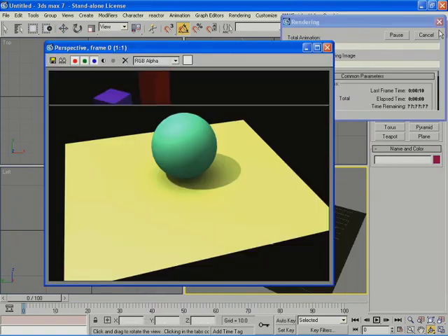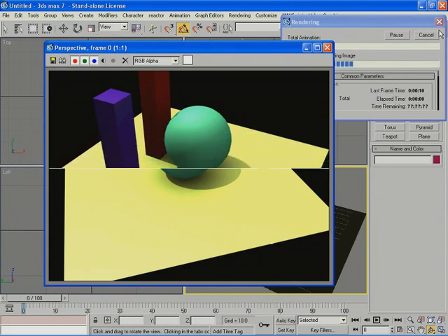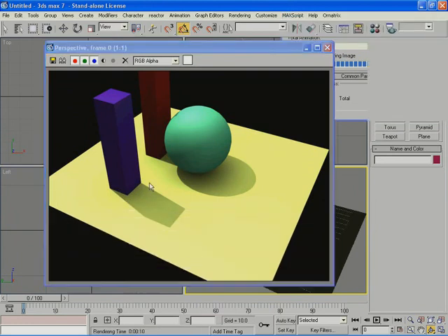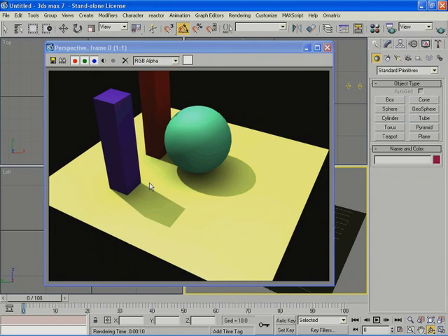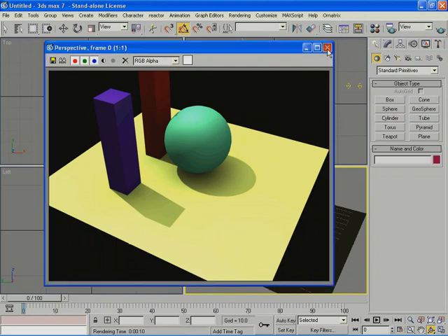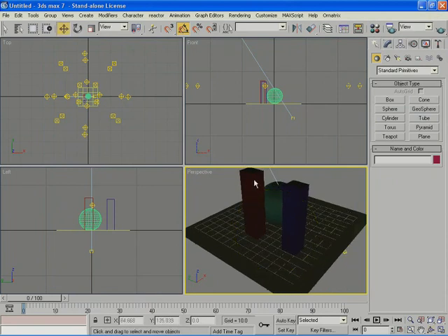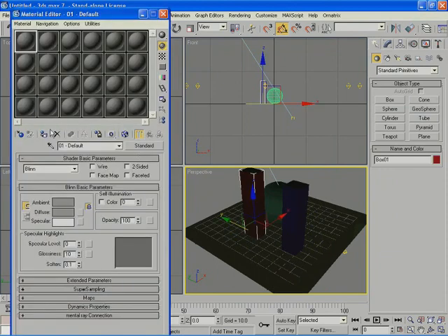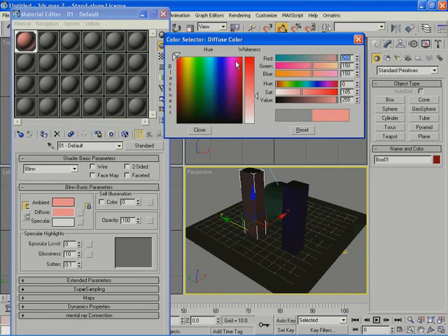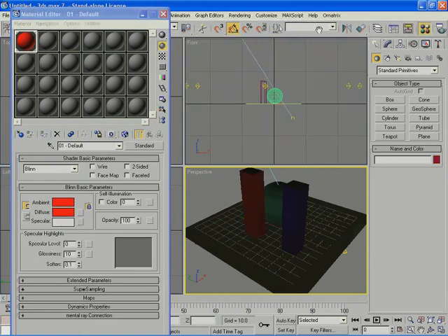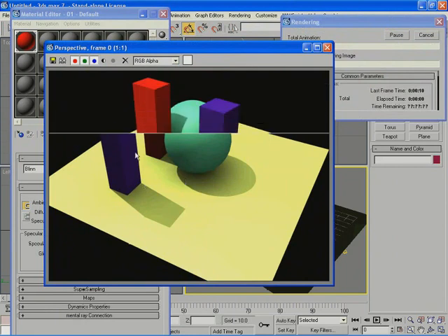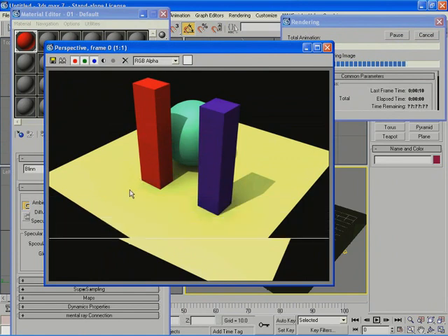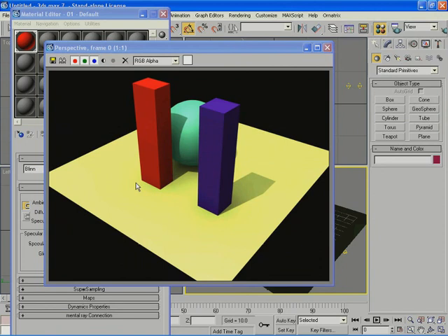But the only thing that we don't get, which we do get in global illumination, is called color bleeding, which is the fact that if you have a red surface, for example, let's say that this box was very saturated red. Whenever you do place this surface in the direct sunlight, the light rays are going to come down here and hit the surface and then bounce back down here. So you're going to have a red reflection on the floor without having the surface be reflective. You're going to have some light reflection on the floor. This is what you get automatically with global illumination, but you don't get it here.